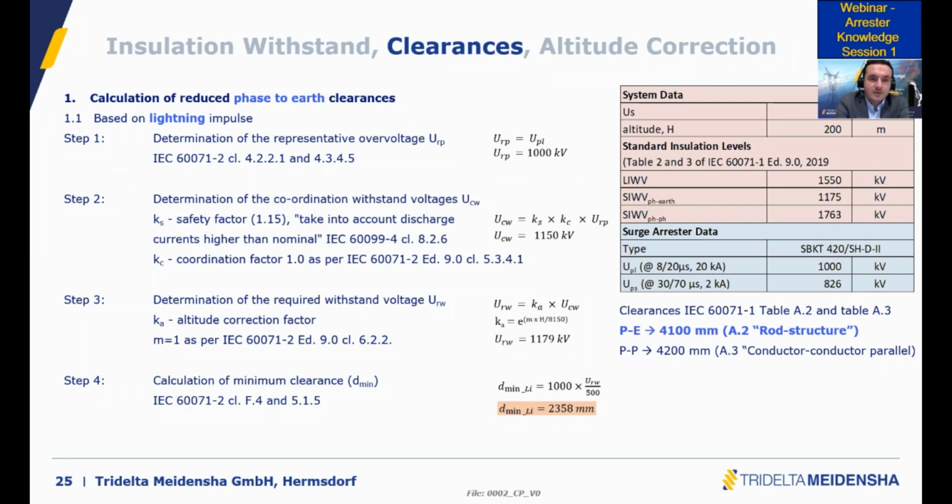Just to give you some information. So in general, I would say surge counters are not needed. Okay, so we will answer later on. But basically, I would say surge counters are not needed. It depends what you want to do with it. If this is for statistics information, if you want to just measure the number of over voltages, this could make sense.